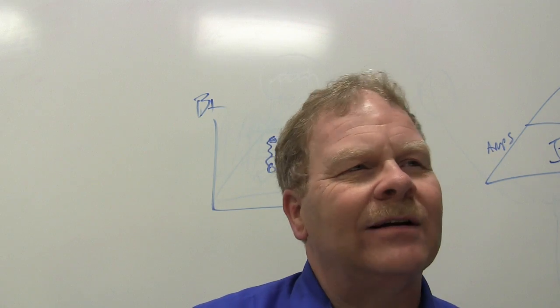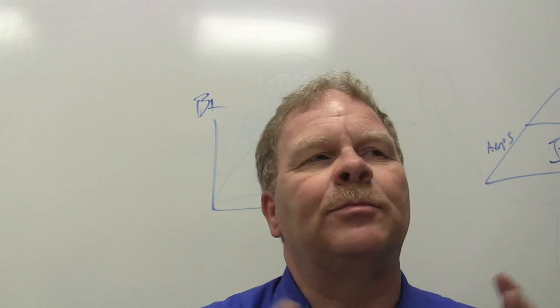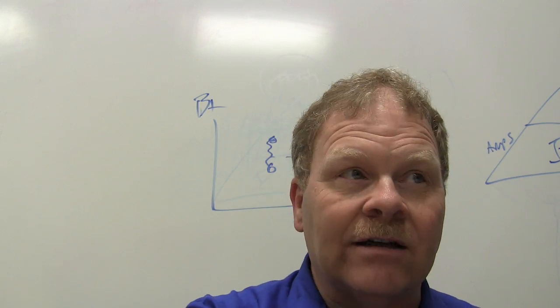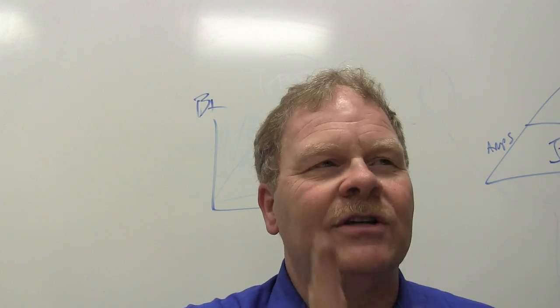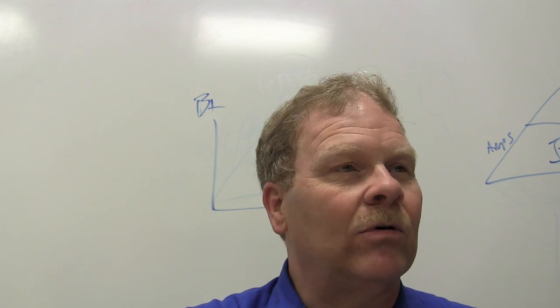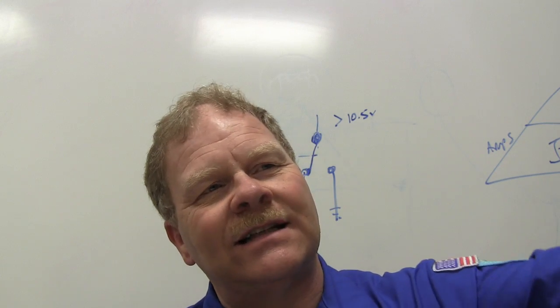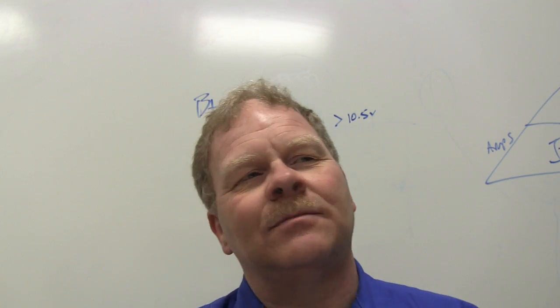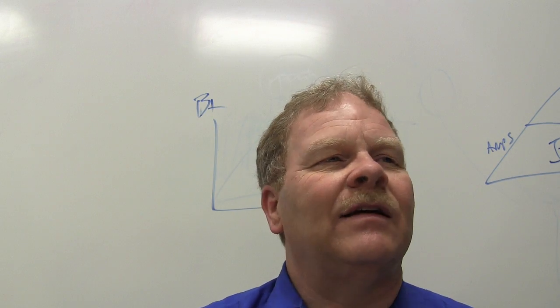That's what a current limiting resistor is, coming out of the engine controller. If you've got an engine controller and it's putting out a 12 volt signal, and some of them do for AC, and you've got switches that short that 12 volt signal to ground, you'd think, well, that's going to blow a fuse or burn something up. But if you have a current limiting resistor inside the controller, all it does is make that 12 volts go away. You got me? All right, now think about this.